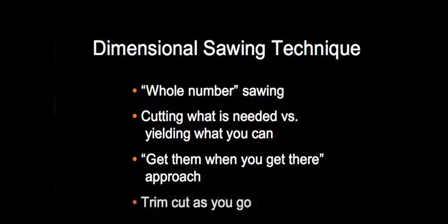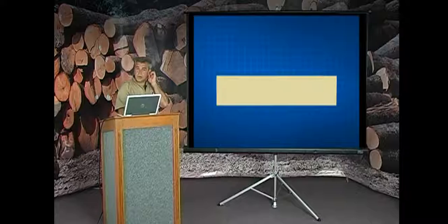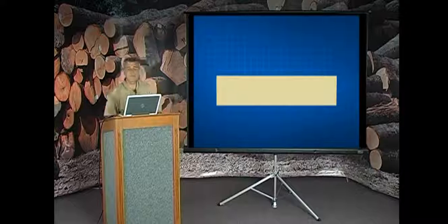Trim cut as you go. I think that's the way I deal with stress in the log the most. Using that technique of trim cutting as I go is probably the most common way I deal with stress in a log. So in other words, you're cutting and that log is reacting to every cut.